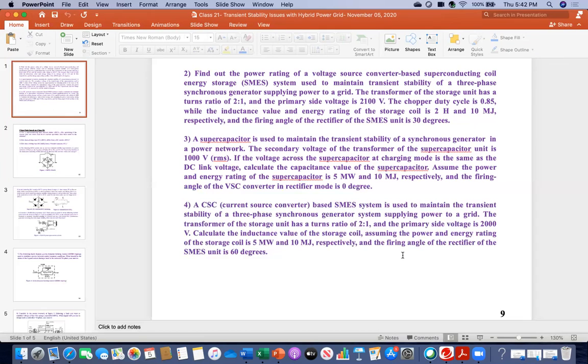I got a different answer, Dr. Ali. Okay, so what is your VDC value? 450.16. No, that is completely wrong. So what equation did you use for VDC? VDC is 3 Vm over pi cosine of alpha. Okay.